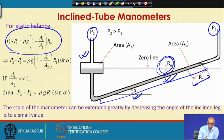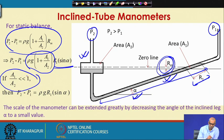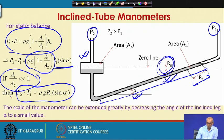R m is equal to R 1 sin alpha. So, P 2 minus P 1 equal to rho g into 1 plus A 1 by A 2 into R 1 sin alpha. If A 2 is much greater than A 1, then A 1 by A 2 will be much less than 1. So, in that case P 2 minus P 1 will be equal to rho g R 1 sin alpha.